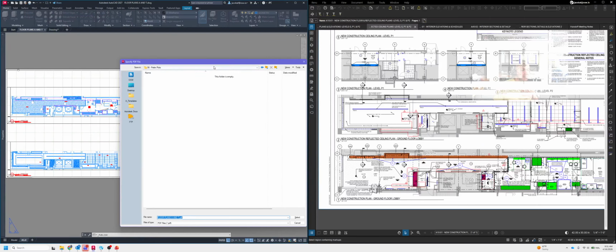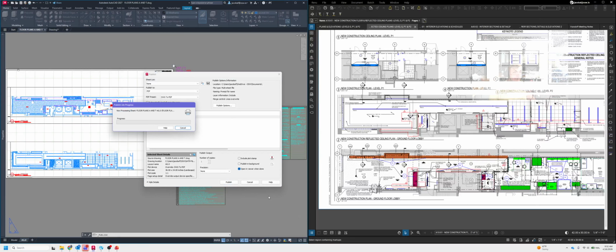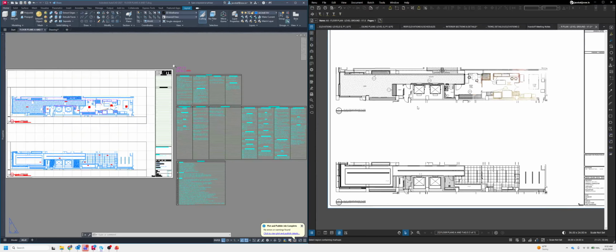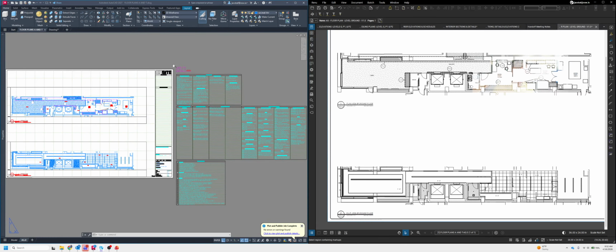And here, again, just like previously, you want to label it like what we were talking about. So AG, AG, and then you can label this floor plan level around. And then you want to label that just like any other drawing with V1.0 for version 1.0. Go ahead and save that. All right, and it should show up in Bluebeam in a sec. So there we go. We got our floor plan, our RCP.